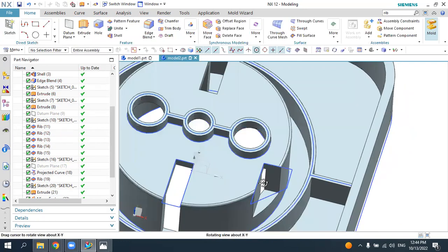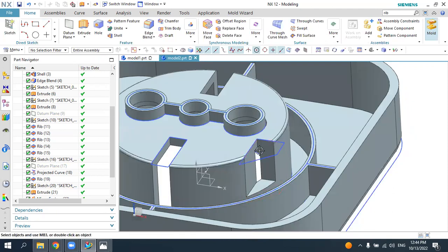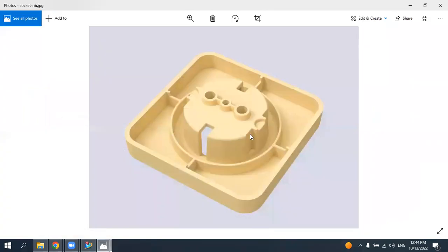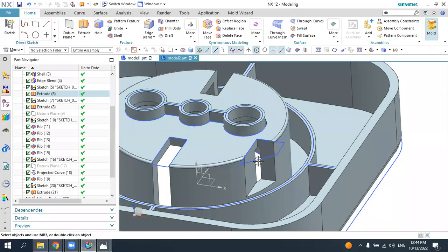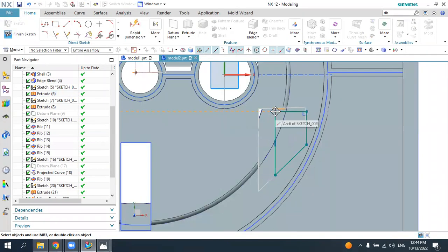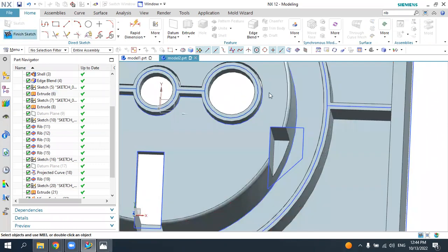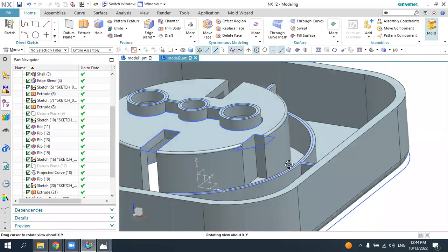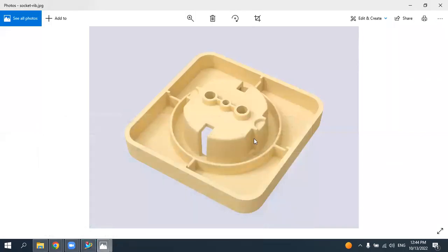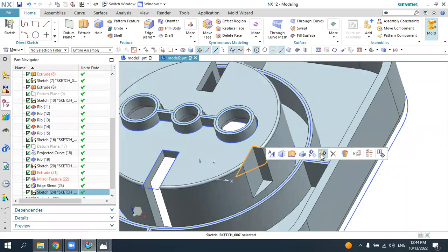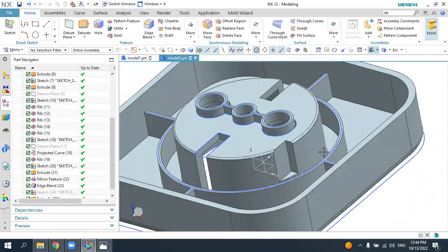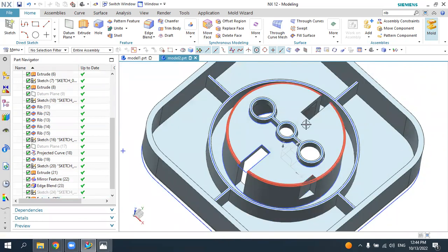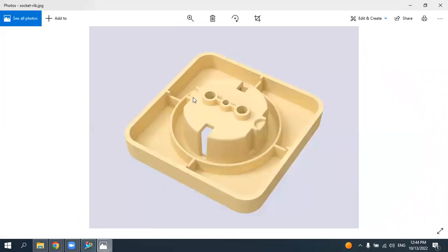Let's press OK. You see this result, but here is an open element, and it means that it is not closed. We can just make some correction on the sketch. We can move here until something here, not to intersect here. And now finish the sketch. More or less the same. Don't worry about the dimension. So the final result is okay. So we can hide this one, and we can mirror this feature on the other sides. You see if you look here, there are other features.